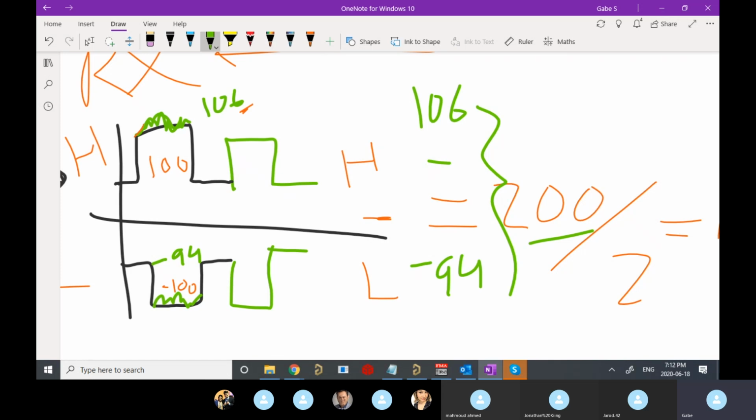They're the same 200, right? So no matter what noise I get on the high line, because I've twisted them so closely, I'm going to get the exact same noise on the low line. And because they're a differential pair, exactly opposites of each other, when I do that comparison and subtract them, I basically get to subtract away all that noise that's identical on both lines. So that's what makes it extremely resistant to noise and really good in a noisy environment like a car.